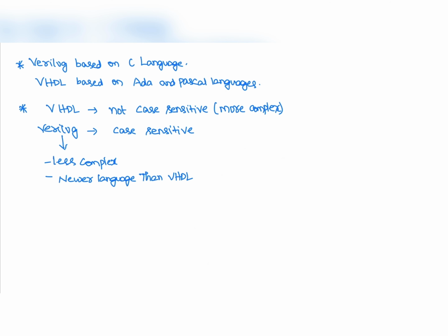Some more points: Verilog is based on C language and VHDL is based on Ada and Pascal languages. VHDL is not case sensitive, but Verilog is case sensitive. Verilog is less complex and a newer language than VHDL. VHDL is complex. Next question.